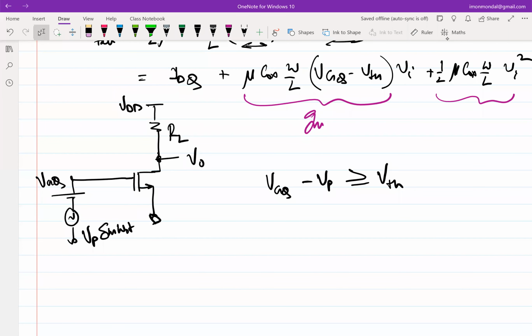And the caveat will become clear if I just say that instead of putting this MOSFET, I use a BJT, for example. BJT is also a source. I can also model a BJT as a voltage controlled source or a current controlled source, doesn't matter. But if we ignore the base current, it's more or less a voltage controlled current source. So now the relationship between I and V in a BJT is, do you recall?